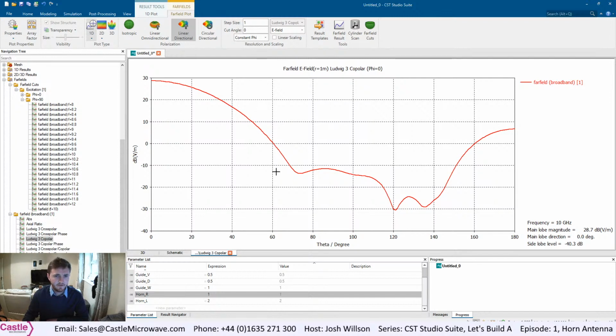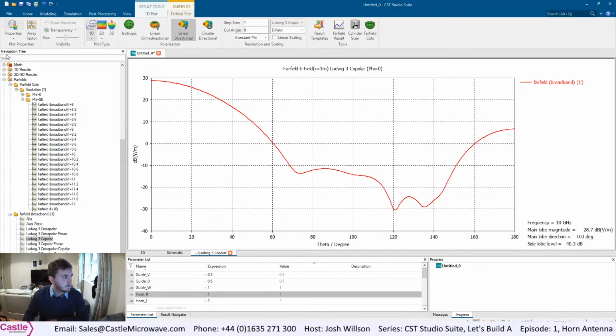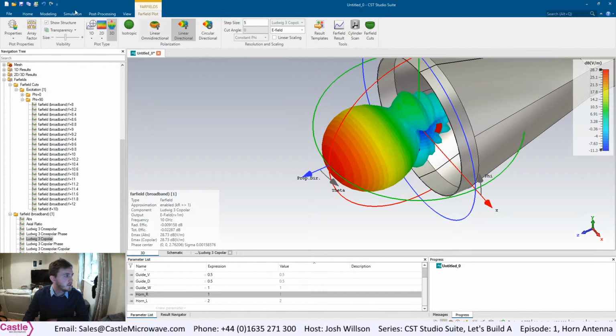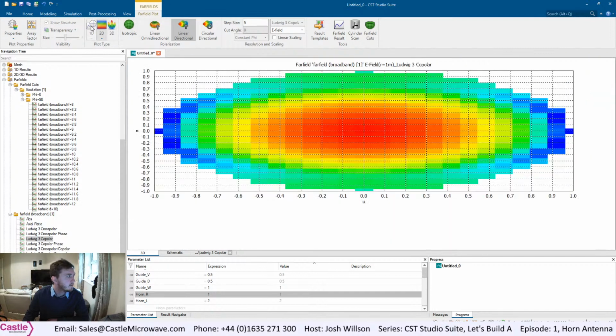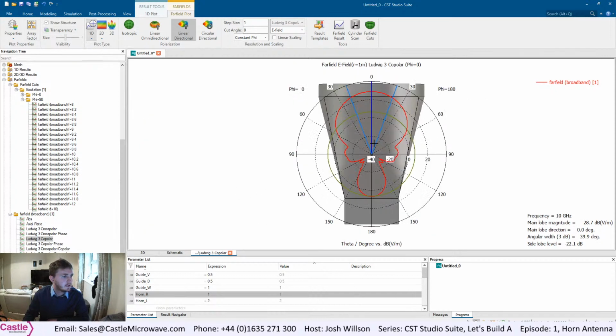The scaling is completely out on this, but really we're looking between this region here, and we can see that the phase is now constant over the Farfield lobe H plane. It's got a little bit rocky at the end, I must admit, because some of the scaling was out. If you need to do this yourself, highlight the area you wish to view and it will snap to view. This can be seen in the Farfield pattern if we go back to 3D. This region here in 2D, undo, polar, here, this 20 degrees region.